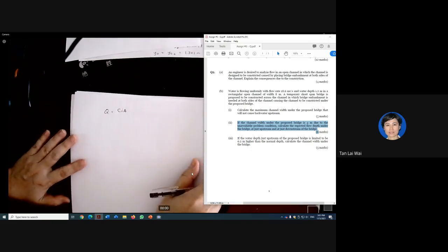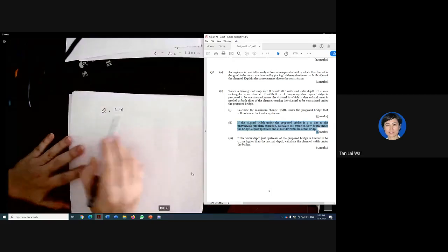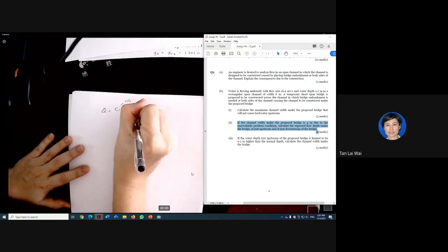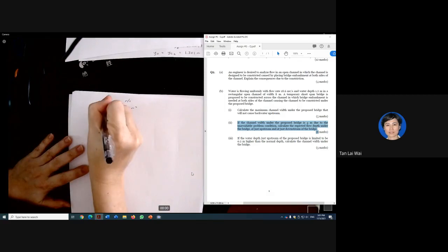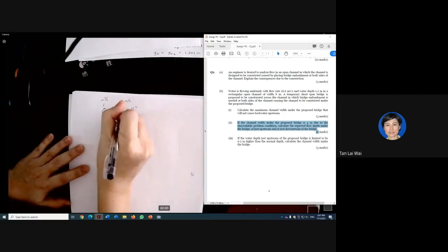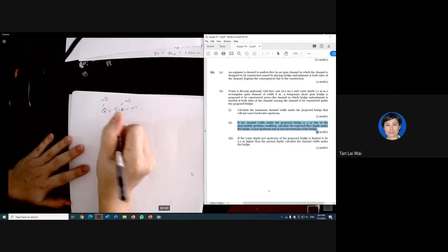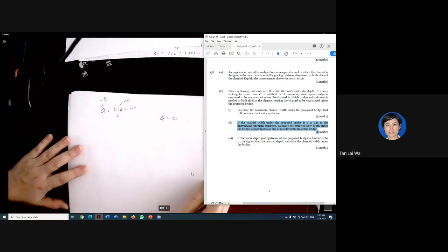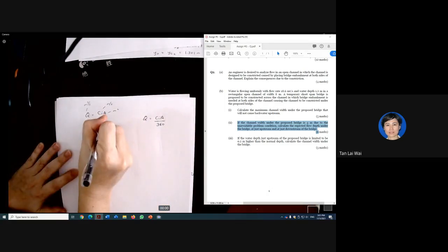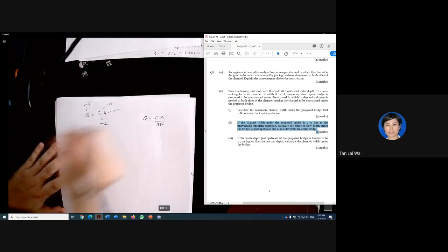As an engineer later, you have to understand this. This is correct if the unit is meter per second and this is meter squared, because this gives you meter cubed per second. This will be correct. But do you realize that your I in that formula is using millimeter per hour and this is hectare? Am I right?